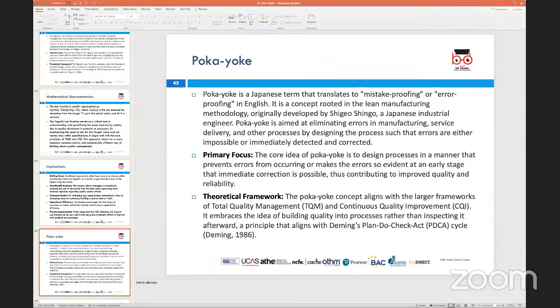In some cases, you would look at the paint variant being a bit thick. So sometimes you would see people who are inspectors or quality insurers wear gloves and they run their hands over the cars across the body of the cars to see if there are any variation. What is that variation? That will be a physical variation they'll be able to pick up, wherein the coating of the paint is applied, which is a bit thicker, but then in some places a bit thinner. And what they would do is reject that product and that will go out.